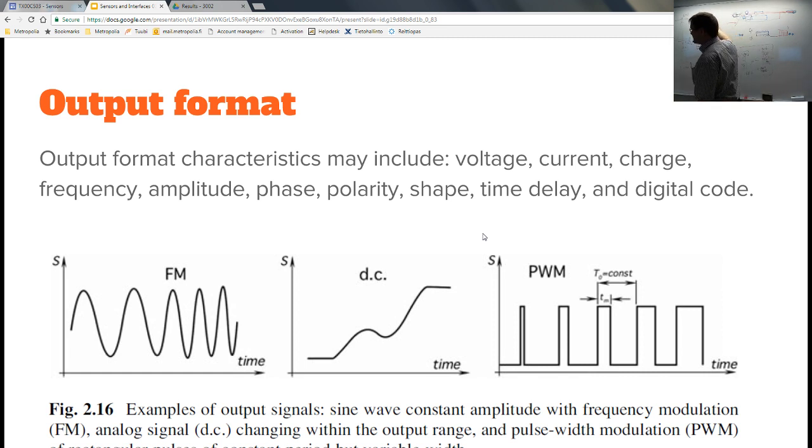And this is the way to do it cheap, since you can have these different capacitors for temperature, pressure, humidity, and then you have just a multiplexer to multiplex different capacitances to one single oscillating circuit, and then you have actually a frequency that you can then modulate with the radio frequency, and there you have a radiosonde.